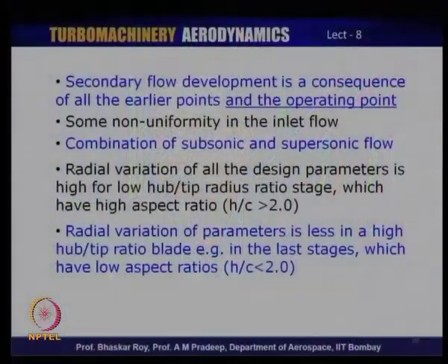And then of course, all of them put together, you have a secondary flow development. It also depends, as I mentioned earlier, very strongly on the operating point. So, you may have a low secondary flow at the design point, whereas at an off design operating condition, the secondary flow may be very strong.